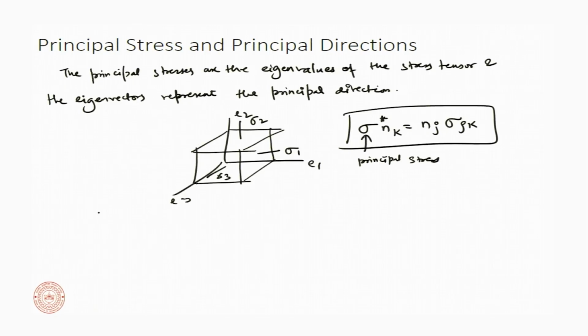So there are three stresses. How do we find the principal stress? You find it just like you would find any eigenvalue or eigenvector. Let me write down that eigenvectors are orthogonal. So we can see that they are orthogonal, or 90 degrees to each other, because our Cauchy stress tensor is symmetric.